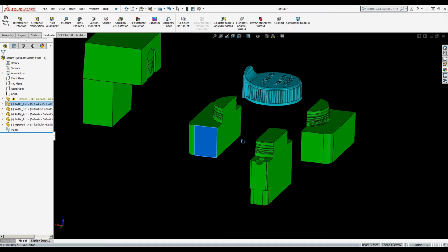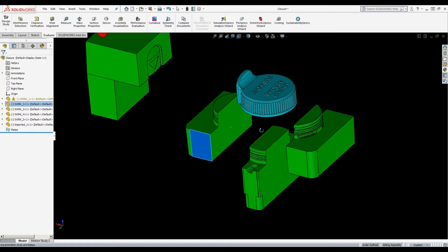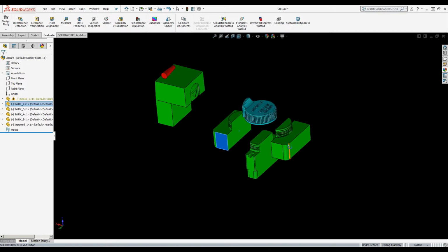What we show here in our prototype tooling is a much more efficient and cheaper version for creating that undercut and demolding part. And essentially proving out the design for the customer to see if it's something viable, moving forward at a low cost. The difference with manual versus auto: manual tools have a lower tool cost and a higher piece price, and obviously the reverse when you go into automatic tooling, you'll have a higher tool cost, lower piece price. So really it's going to depend on your project and what your needs and expectations are.